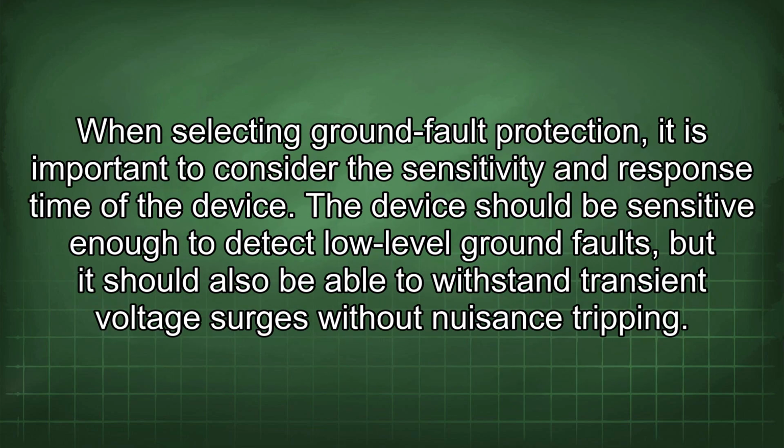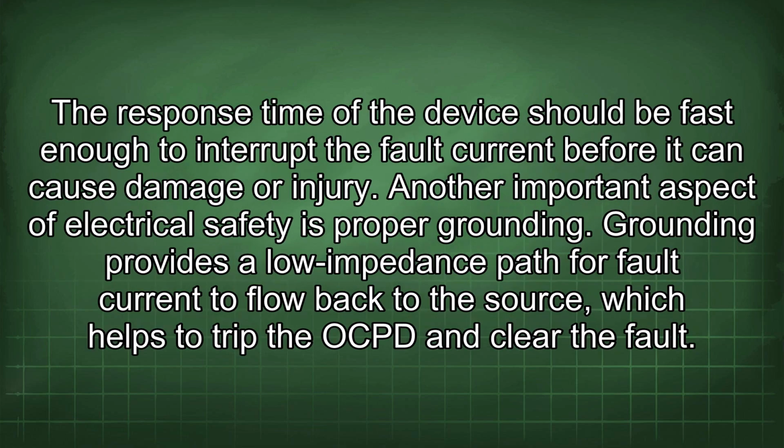When selecting ground fault protection, it is important to consider the sensitivity and response time of the device. The device should be sensitive enough to detect low-level ground faults, but it should also be able to withstand transient voltage surges without nuisance tripping. The response time of the device should be fast enough to interrupt the fault current before it can cause damage or injury. Another important aspect of electrical safety is proper grounding.